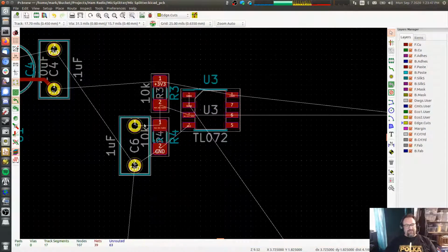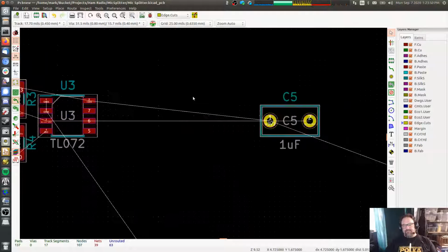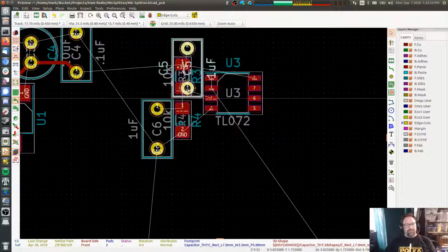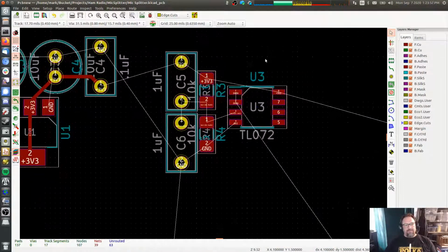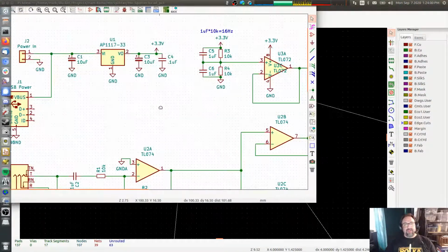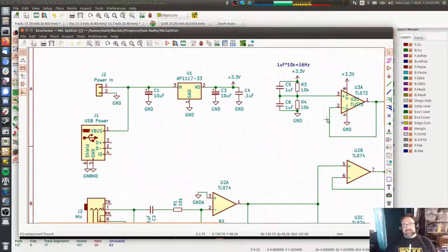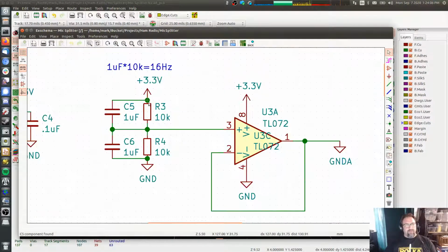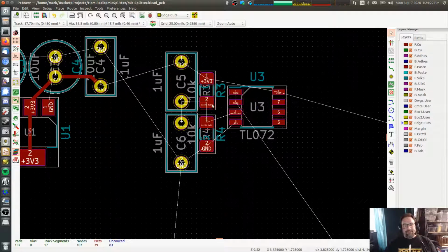All right, so the considerations I have here are that I'm thinking about rework on this board. So let me bring in the schematic and show you the schematic part. I have different size screens, so it's kind of doing weird things. So I'm looking at this. We've got 2 resistors in a voltage divider with a couple of capacitors on either side bypassing it, and then we need the center part to go to the V+ terminal. The reality is that this doesn't actually matter, but you generally want to make sure that your current passes across the capacitors before it goes to the load, right?